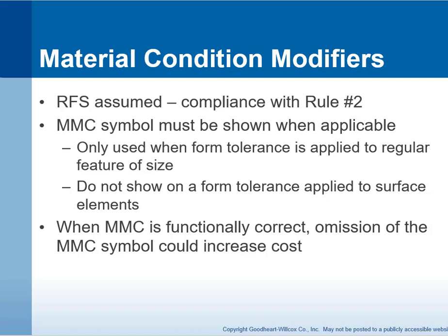When an MMC is functionally correct, omission of the MMC symbol could increase cost. Again, RFS is always assumed unless an MMC modifier is present. Okay, RFS is a little bit more stringent, so MMC modifiers, if they're applicable, should be specified because part costs can go up.